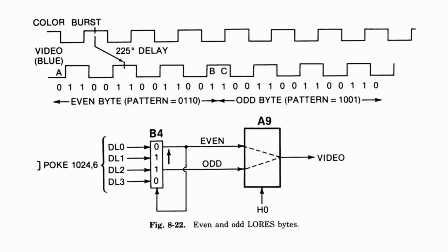Remember that there are 7 text mode pixels per character, but that the color burst signal is half this speed. This means that even and odd-numbered columns are 180 degrees out of phase from each other. While Woz could have fixed this in software by insisting you use color 1 in even columns and color 4 in odd columns, he fixed it in hardware by generating different waveforms for even and odd bytes.